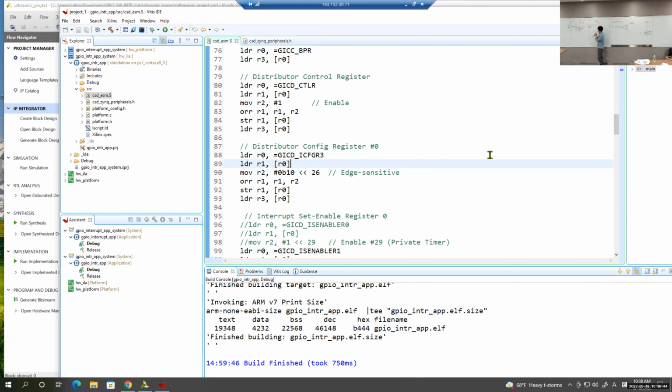Okay. Then last time when I showed you a demo, if I don't clear that bit, you push up the switch, then the interrupt line goes up. If you don't clear the line, it is the same line as in the other case. If you don't clear this bit with the software, then it keeps the circuit high forever.